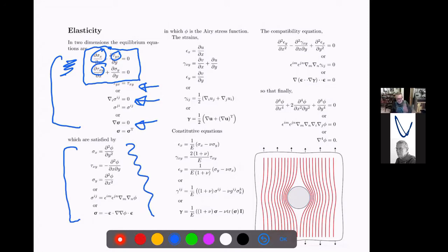The area stress function is used quite a lot in shell theory, where what you do is you use this 2-dimensional analysis in plan. So you look down on your shell structure, and what you see is a 2-dimensional structure in equilibrium in a horizontal direction. And all these equations remain unchanged. Well, the equilibrium equations remain unchanged. The other ones do change.